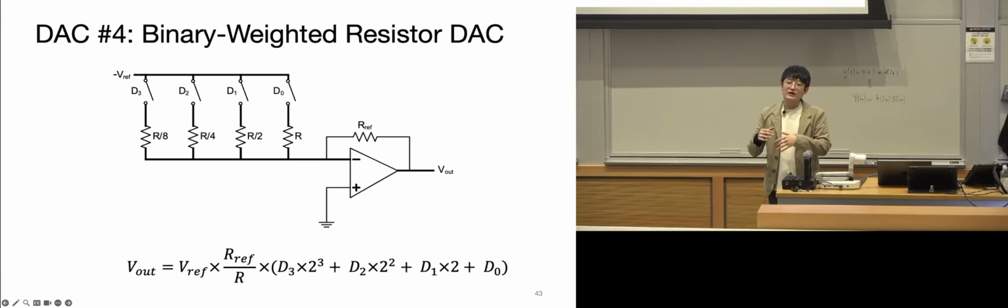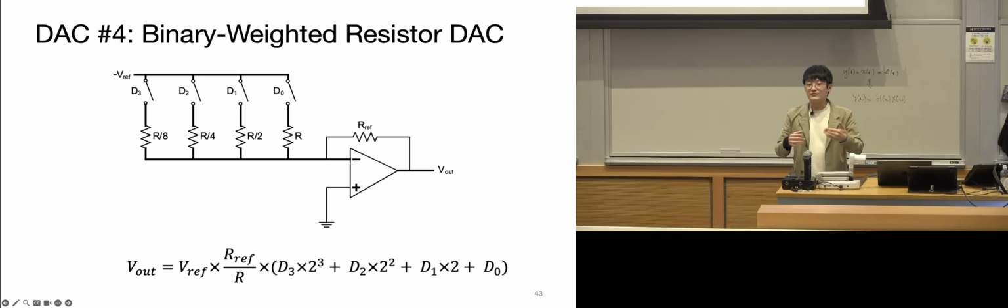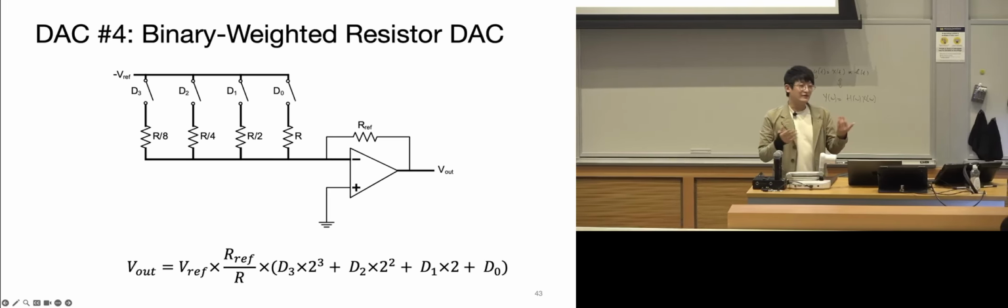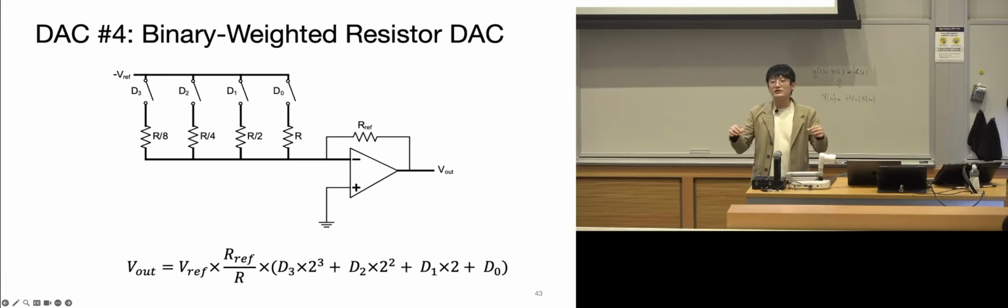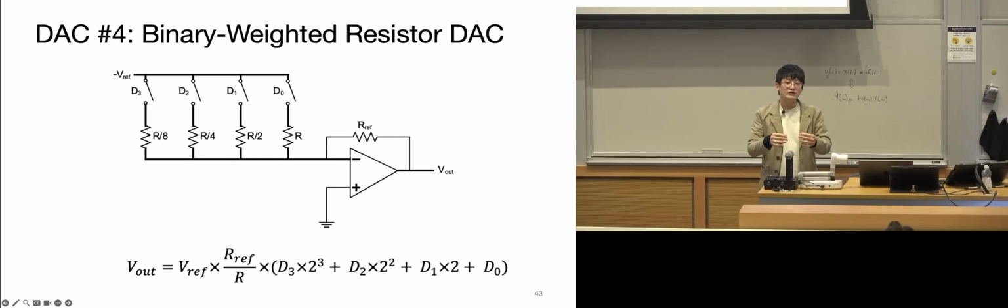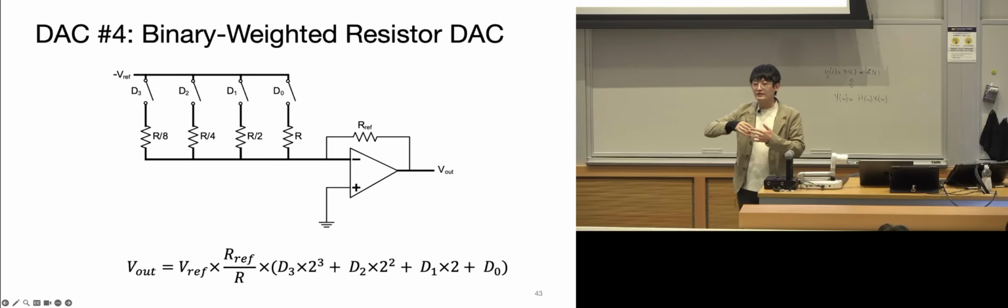For example, if this 1K resistor you manufactured is actually 995, which is pretty okay, then chances are that the entire batch is 995 or very, very close to 995. So as long as you use the same batch of resistors, even though the actual value has slight variance, you can still have a very precise voltage divider.